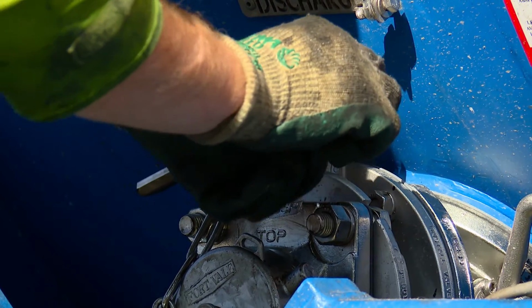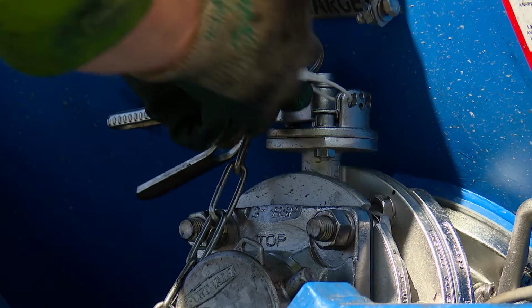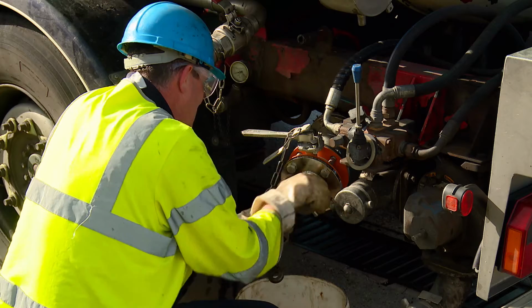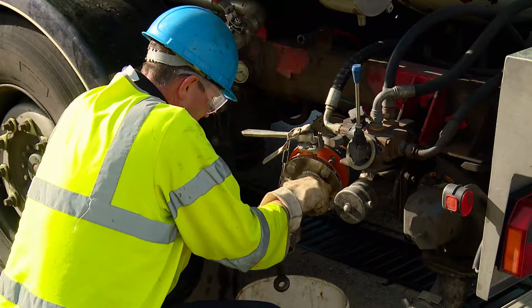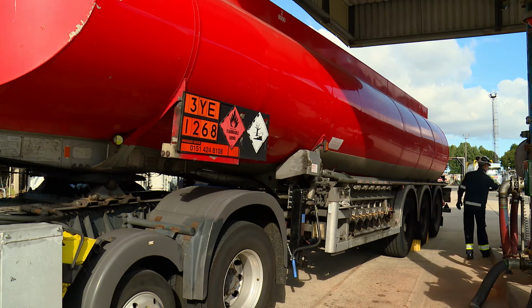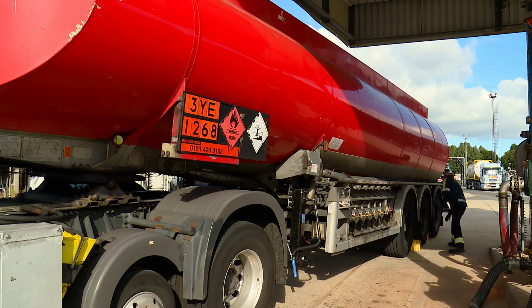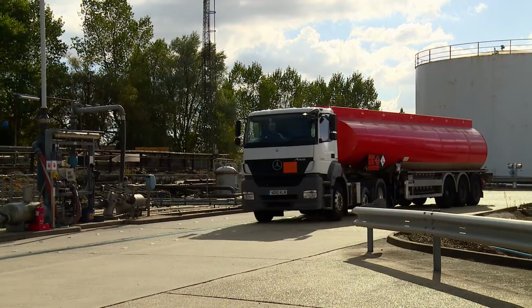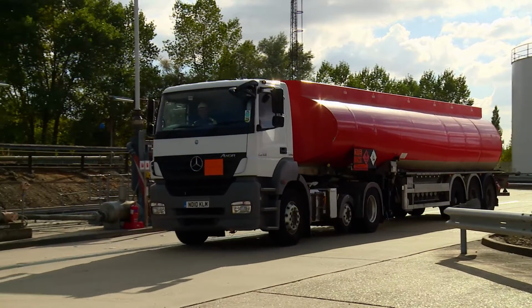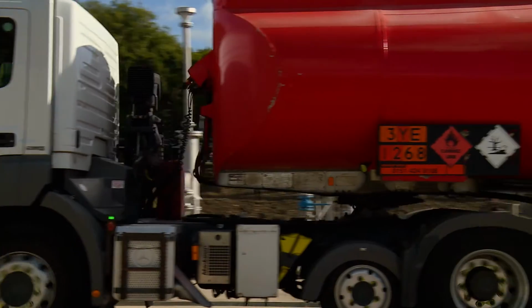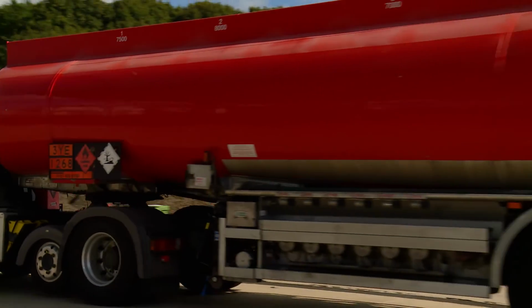Where applicable for loading, security seals are placed on the vehicle discharge valve and the seal numbers written on the dispatch note. Before leaving site and entering the public highway, all valves and vents are closed, flanges capped, earthing strap disconnected, and wheel chocks are removed. The driver will perform a final vehicle check prior to departure, ensuring that everything is disconnected and that the area is clean, tidy, and dry. PPE used for the loading procedure can now be removed.